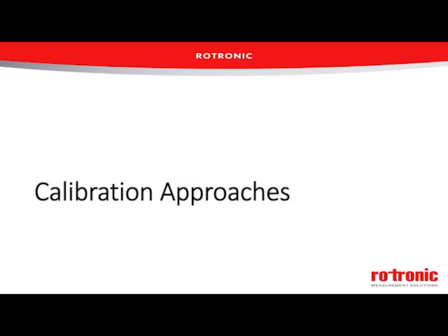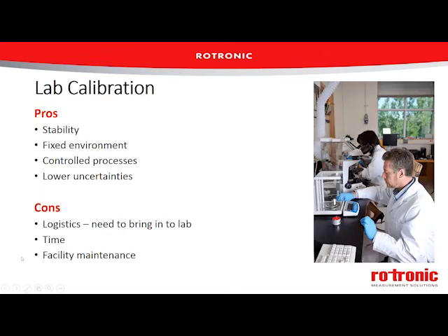Bruce, can you maybe guide us through a few of the common approaches to calibration? Yes, there's two primary approaches to calibration. One is that we're going to talk about today, and we're not going to go into a depth of the actual process, just the pros and cons of each one, so we're aware of what they are. The first one is a lab calibration, and obviously this is where you remove an instrument or you take an instrument out of its normal place and you send it to a controlled laboratory space.